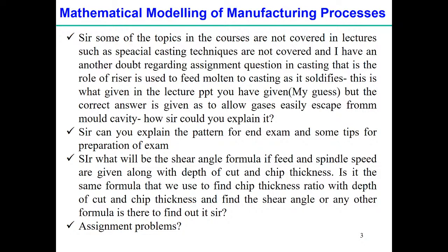we derived the very basic relation assuming some chip thickness in an orthogonal cutting situation. We explained the two-dimensional figure and then presented the chip thickness and the width of the chip. From those values we estimated the relation of the shear angle with the other parameters.